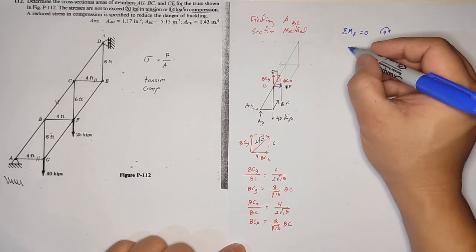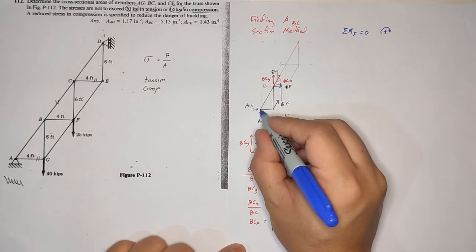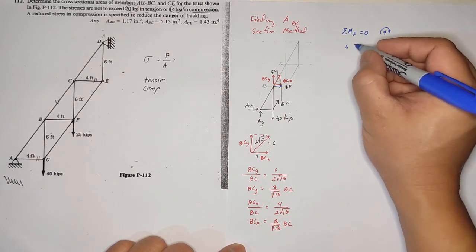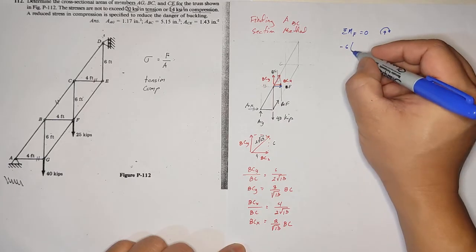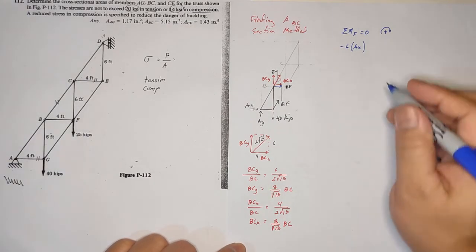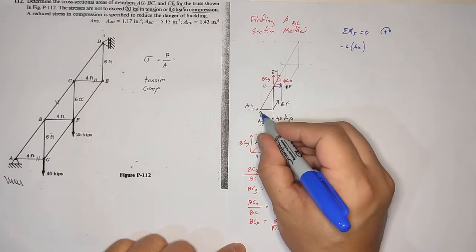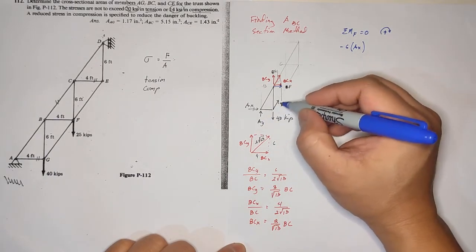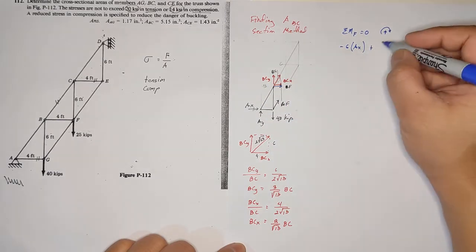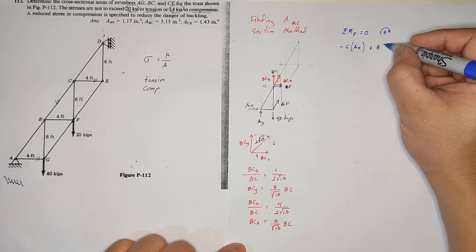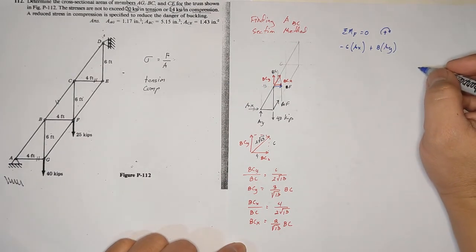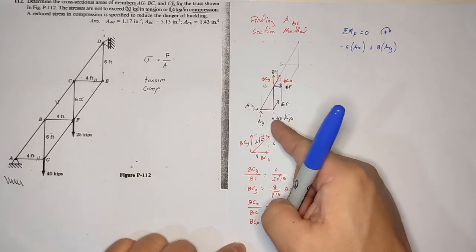So this is counterclockwise, and the perpendicular distance is 6, so that is negative 6 AX. Okay. Then here to here, that is 4, 4, that is 8. So that is clockwise. So 8 times AY. Okay. Then what else? 40.